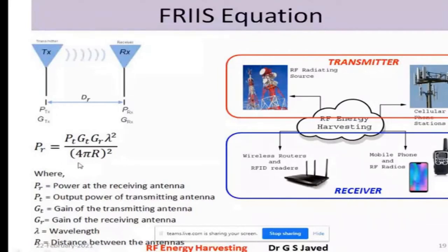and this is actually squared. The reason it is squared is the power depreciates or falls down significantly because the air in the system absorbs some of it or it dissipates a lot of it. And this is directly dependent on what is the frequency of the system. So 4 pi r by lambda, whole squared, is the actual equation which looks at what is the impact. So the amount of power dissipated is directly dependent on the lambda.